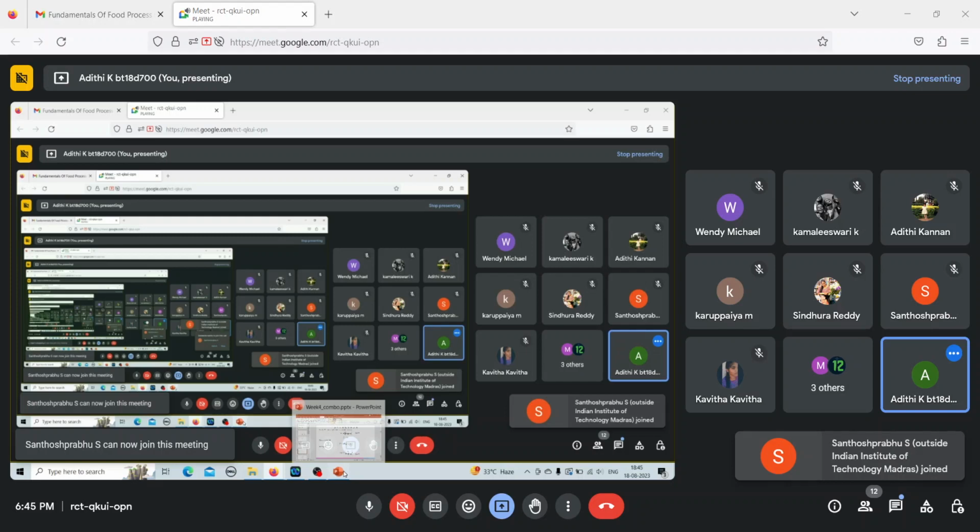So now we know what is delta T, which is Ts minus T3. It is given in the question as Ts is 375 Kelvin. The temperature of the last effect is given as 315 Kelvin. So Ts minus T3 is 60 Kelvin. So delta T1 is equal to delta T, which is 60 Kelvin, into 1 by U1, which is 1 by 2950, divided by 1 by U1 plus 1 by U2 plus 1 by U3. That is 1 by 2950 plus 1 by 2100 plus 1 by 1450, which will give me 13.52 Kelvin. This is delta T1, this is not T1.